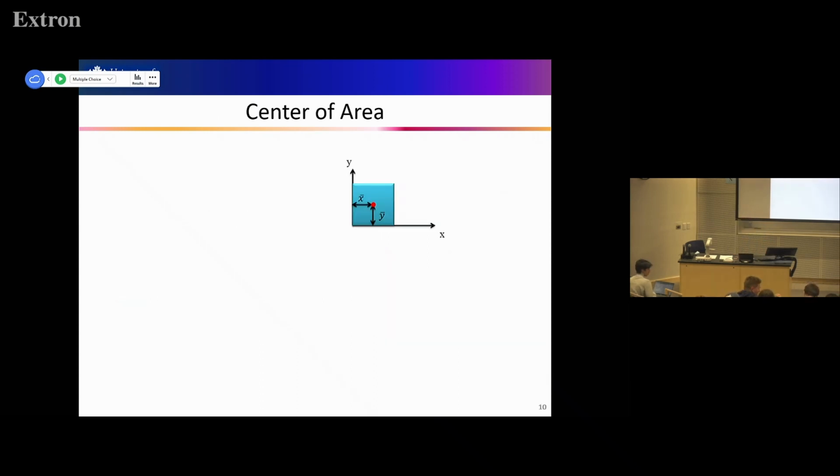Okay, so now let's move on to the equations part, very important. Center of area, so the centroid equation. This equation is what I showed you before, right? X bar is sigma x bar times A divided by the entire area. And we just finished the clicker quiz showing that QY is x bar times A, right? So x bar times A is QY, so this is the same as sigma QY over A.